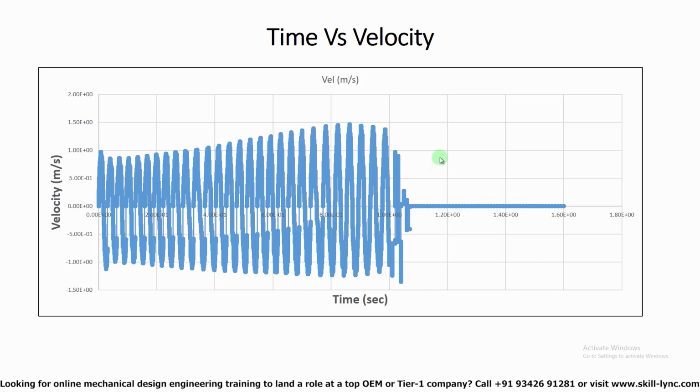So this frequency helps us identify the cyclic load on the valve. Now this cyclic load information can be used to run a fatigue analysis using a structural solver on this particular spindle, and that can be used to predict the life of this particular proportional valve. Now in this particular case there are a lot of things that we have not modeled accurately, so we will be discussing that. But in general, if all those modeling assumptions have been ruled out and if the simulation is set up very similar to a real valve, then this is the data that engineers would be requiring.